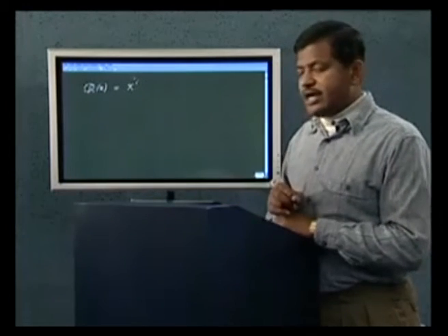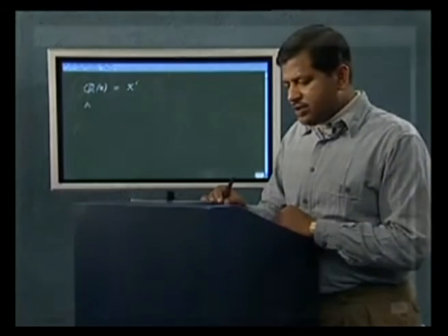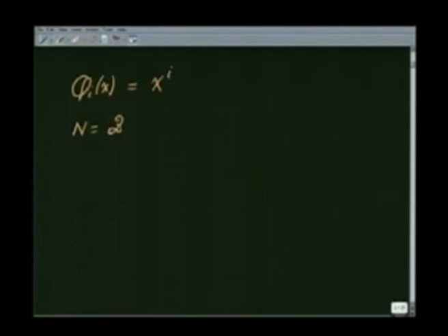So let us take a two-term solution, n equal to 2. So u2 of x is equal to a1 phi 1 plus a2 phi 2. Substitute it back in our variational formulation and get the equations corresponding to a1 a2.